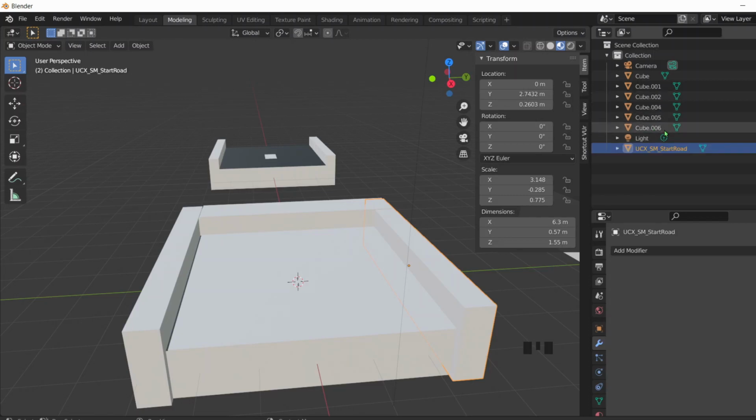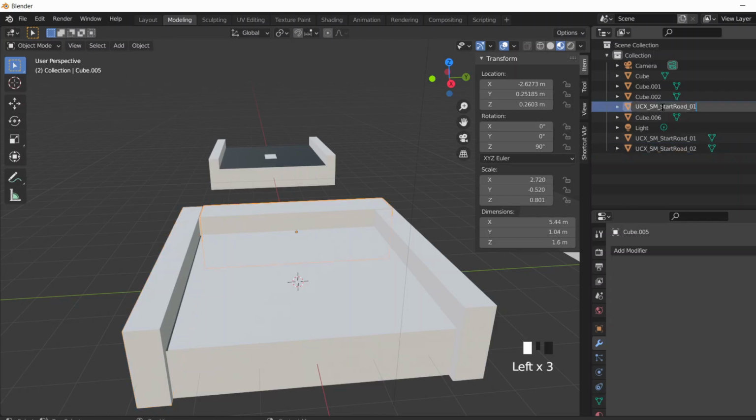So now that I have that, I'll do that for the other two. Since there are multiple objects in here, I'm going to use the descending order collision naming convention. So I'm going to copy this name and then just have it renamed O2. What specific mesh gets named O2 and O1 doesn't necessarily matter. The only thing that does matter is them having different numbers. So from here, we have the four collisions of our static mesh.